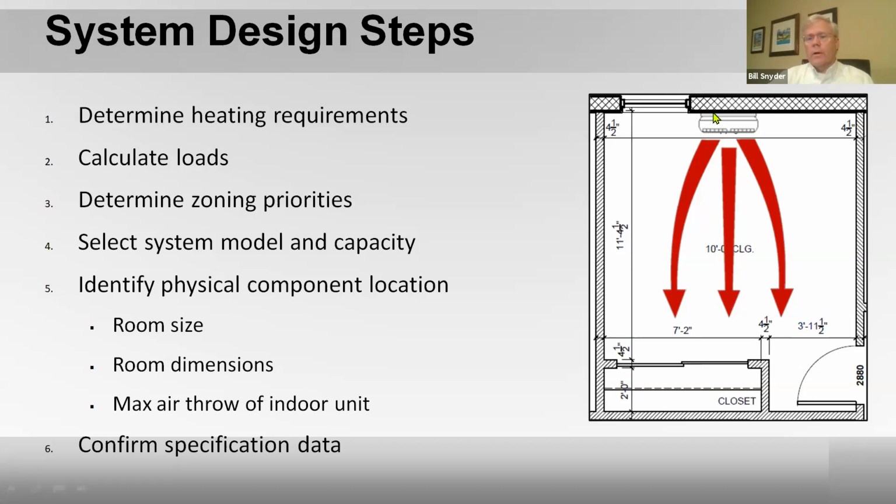Also consider the airflow, how far you have to push this. At 11 feet, I think any of our equipment will handle this type of room without a problem. But if you get into a big great room or something, maybe the little wall unit isn't the correct thing to cool the whole space, or maybe you have to put 2 in there. Maybe you have to use a ceiling suspended unit and push that air across the whole room.